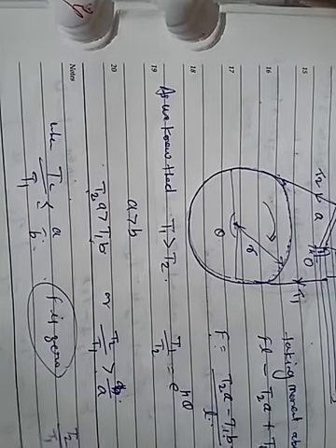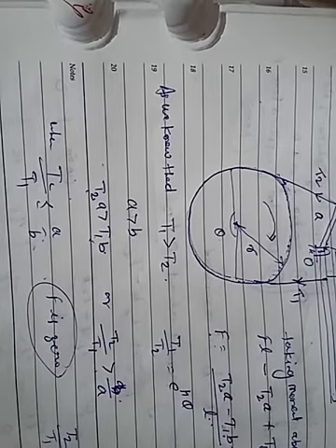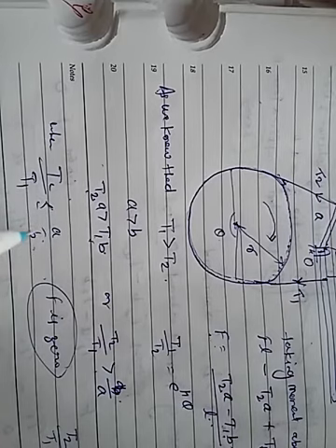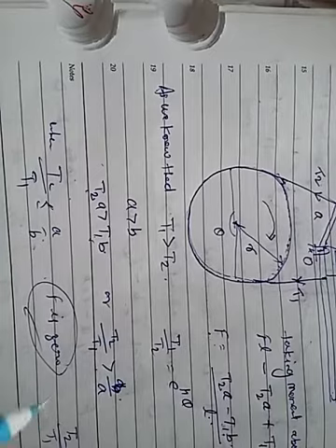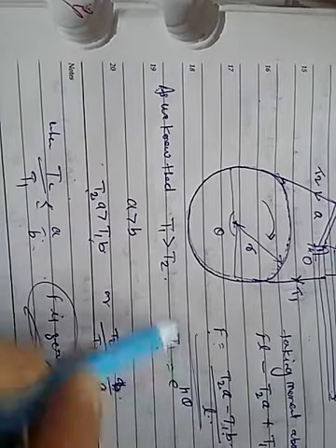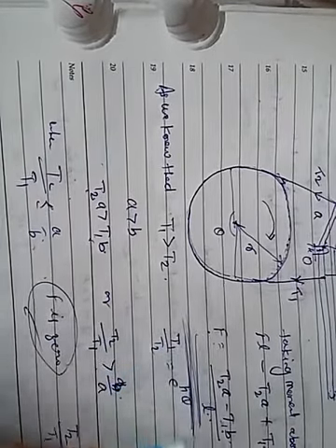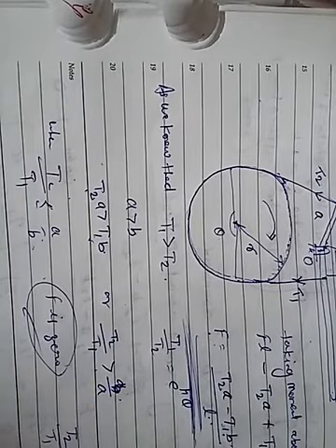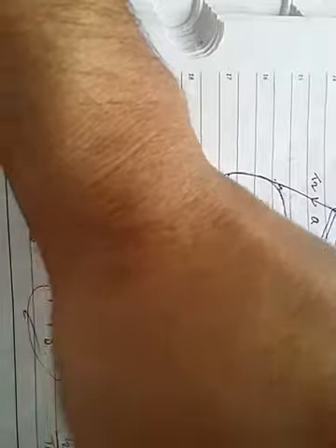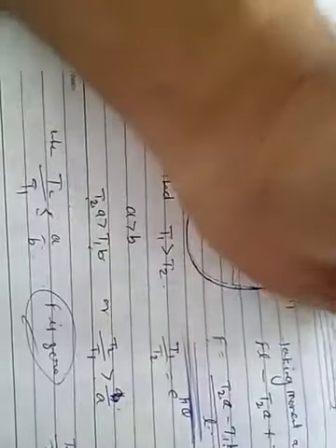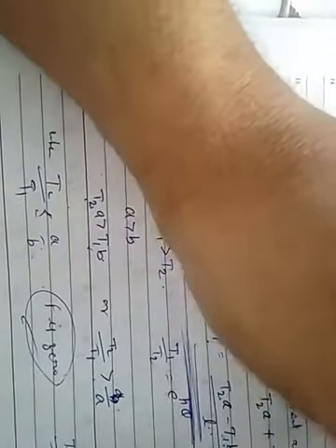Sometimes it's T1 by T2, and F is negative, when this value is large. So when F is 0, this becomes a self-locking braking system. The brake becomes self-locking, as no force is needed to apply the brake, and once the brake has been engaged, no further force is required to stop the rotation of the drum.